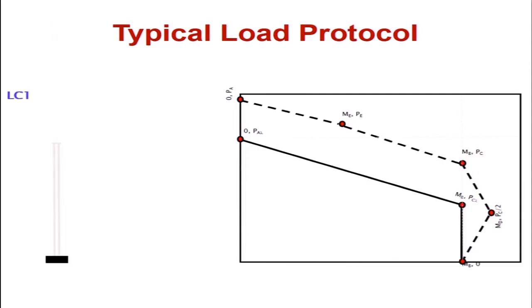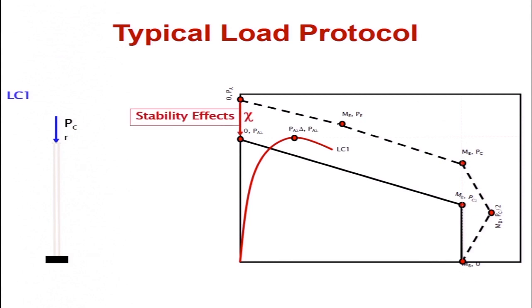So we started by looking at our usual interaction diagram and doing basically a buckling test, which is shown there by that red curve. Again, because of initial imperfections and other things, of course, you never go straight up the vertical axis, but you do get very close to the actual buckling load up there. And so that was the first test, and that was to basically try to tease out all the stability effects.